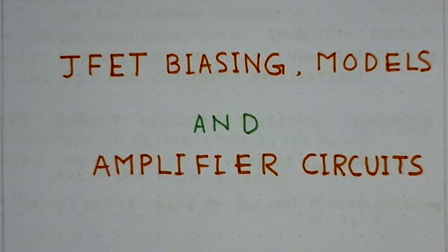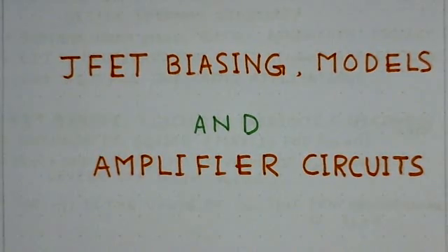Small signal models for low frequency and high frequencies differ only by additional capacitances added to each pair of terminals in the high frequency model. Note that the current gain in junction FET amplifiers is undefined, so there are only three amplifier parameters: voltage gain, input resistance, and the output resistance.